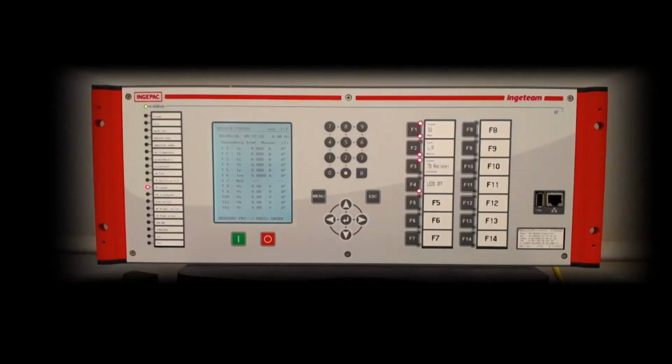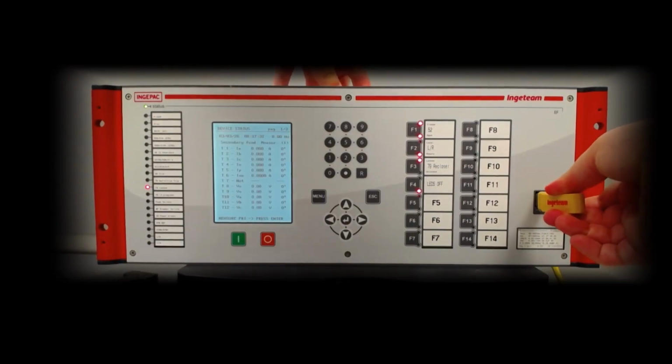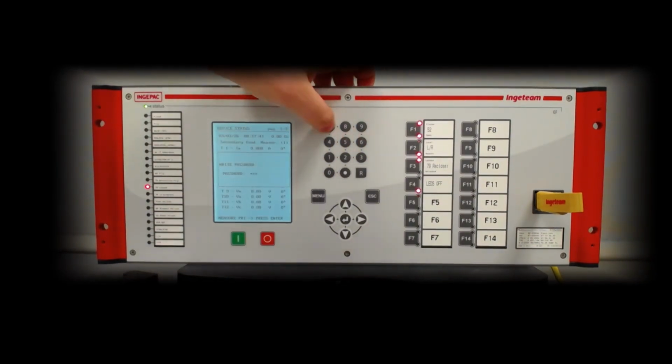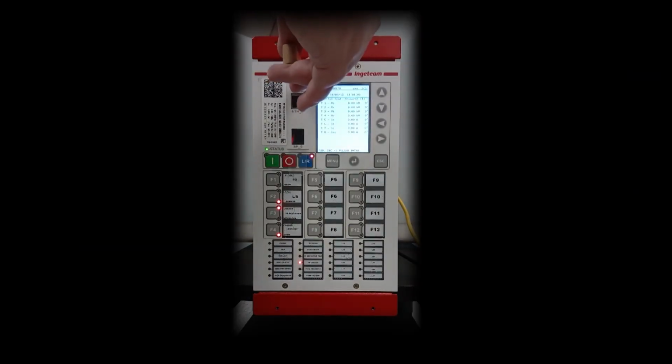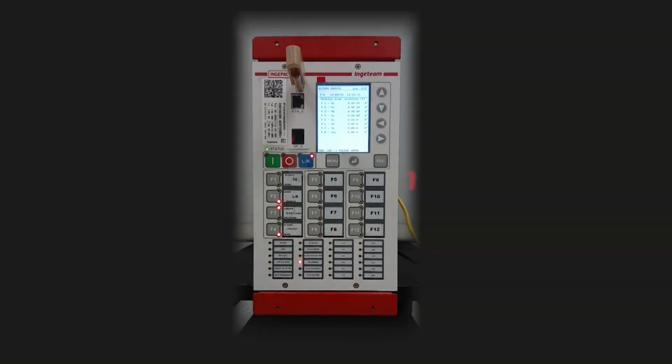On the contrary, the numeric type key will be input differently in the Ingepack DA and EF devices. The Ingepack EF devices do have a numeric pad with which to input the key. Nonetheless, we will need to follow the instructions shown in the local display for the Ingepack DA devices. These will indicate the user that the menu button needs to be pressed to use the functional keys as a numeric pad. Finally, we now know what can be done through the USB port of an Ingepack IED and how to configure and restrict its use.